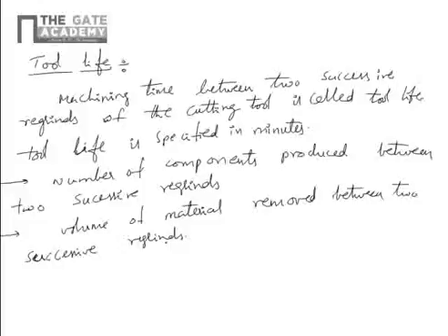Factors which influence tool life. Generally properties of the workpiece material affect the tool life. If the hardness of the workpiece material is high, tool life will become lower. The higher the cutting forces, the lower the tool life. The higher the tool wear, the lower the tool life.